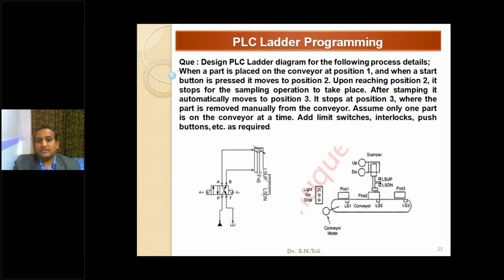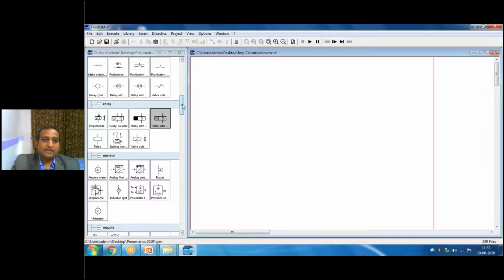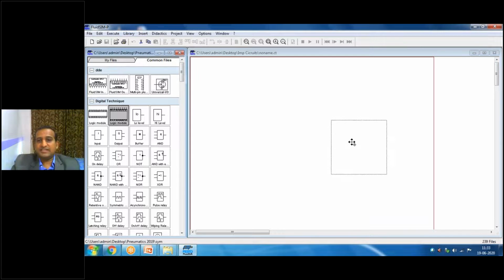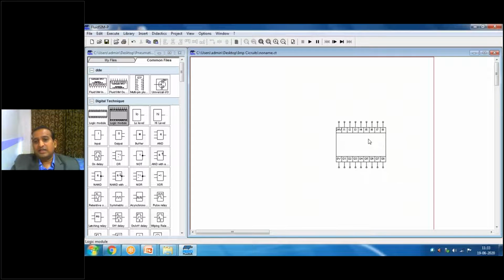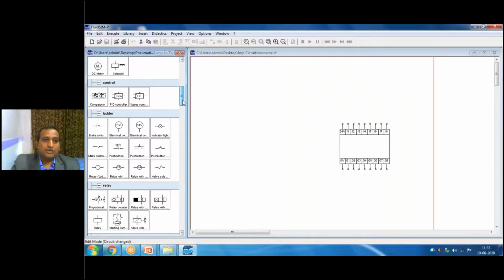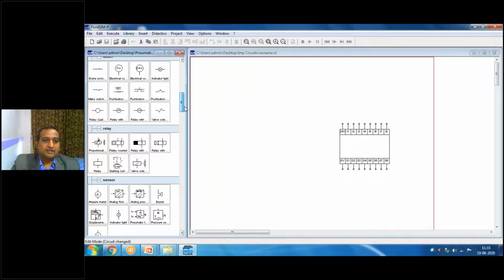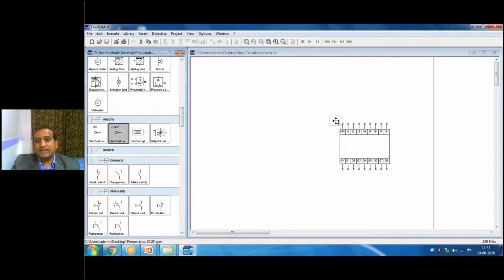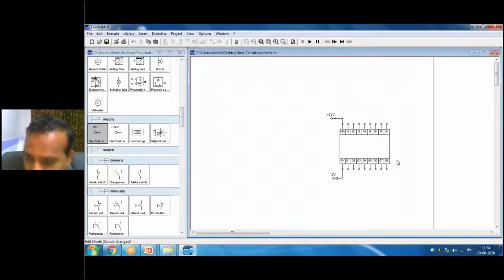Okay. So these are all the stamping machine PLC. Here PLC is available. Two PLCs, you can select any one. The PLC requires 24 volt and 0 volt. First I'll give 24 volt and 0 volt, without which it is not starting, because this is also a passive element, and it especially requires DC volt, not AC volt. Here it is showing I1, I2, I3, I4, I5, I6, I7, I8 are the inputs. Q1, Q2, Q3, Q4 are the outputs. In some PLCs it will start from Q0, Q1.